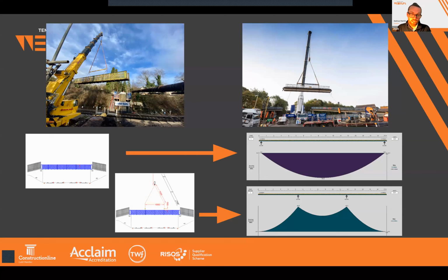So another point I briefly mentioned there was the condition of the structure. If we are keeping the forces within the structure as what we're happy with from a theoretical standpoint, then we need to consider the condition of the structure. If it's corroded or on dilapidated structures, then we need to consider those reductions in cross-sectional area or damaged connections, which could result in a significantly reduced resistance to those members.